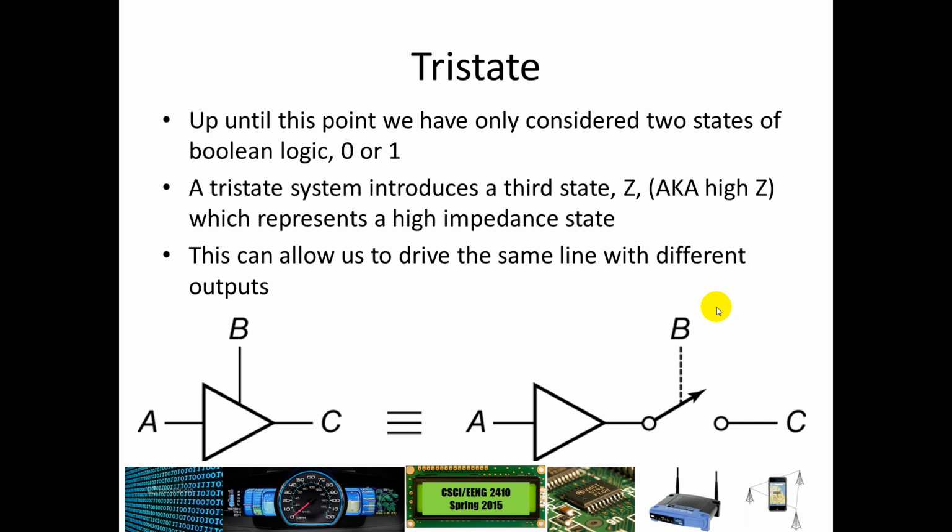So in that case, what you would want to do is establish a high impedance between the FM radio and the output speaker, so long as the FM radio is not the source that is selected. So in this case, we can represent that using a buffer like this, and that buffer has an extra select line B.